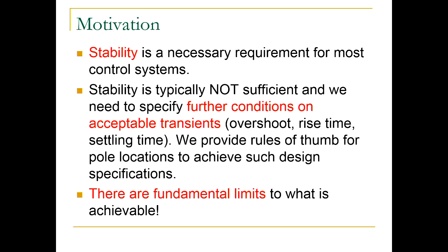So you change from 0 to 25 desired temperature, and it takes 5 years to go from like 0 to 25. That's not acceptable. Similarly, if you have overshoot that's going to 100 degrees and then settles at 20, that's also not acceptable. So in every system, depending on the application, you can define meaningful desired specifications. What is a good system in that specific case will depend on the application, right? And what you want to achieve, right?